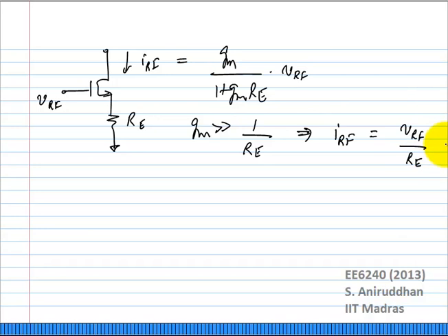However, remember the resistive elements on an IC are generated using diffusion, right? Doped silicon, either in the substrate diffusion, maybe an N-well, or the polysilicon. All of these will most probably have some kind of voltage dependence, and therefore this is not necessarily 100% linear, but it will be much more linear than your MOSFET. That much you can say. So this is one possibility.